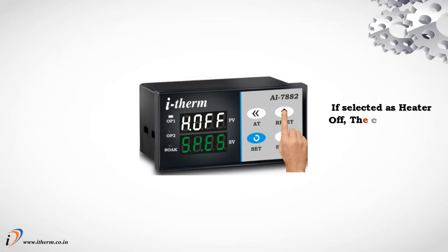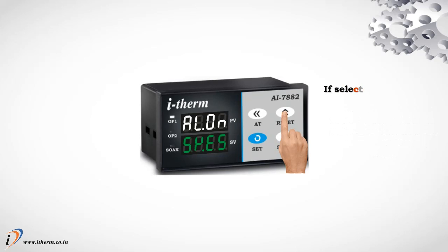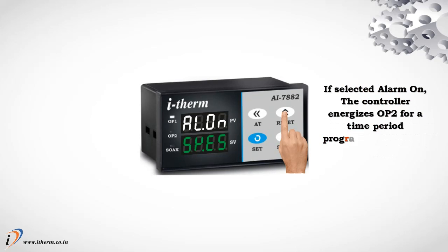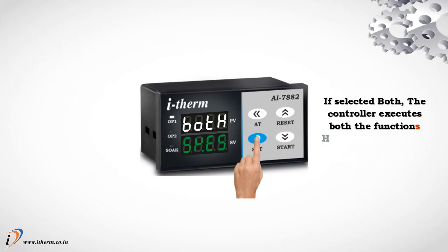If selected as heater off, the controller de-energizes output 1 as soon as the soak time is over. If selected alarm on, the controller energizes output 2 for a time period programmed via soak time delay parameter at the end of a soak time cycle. If selected both, the controller executes both the functions heater off and alarm on as described.